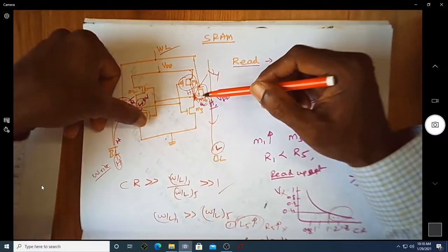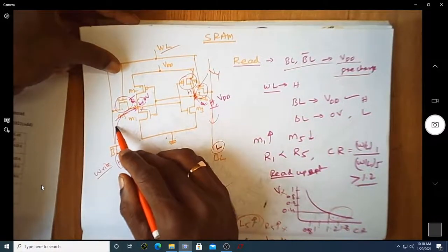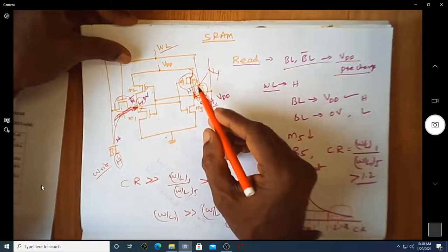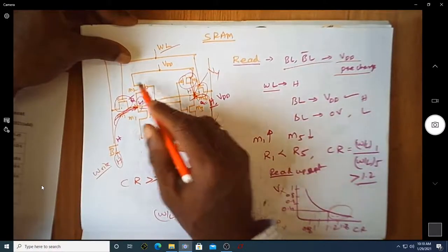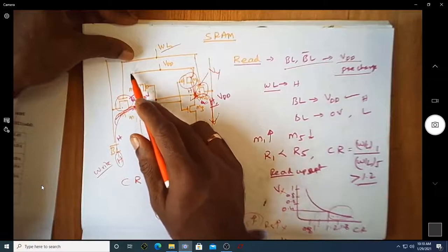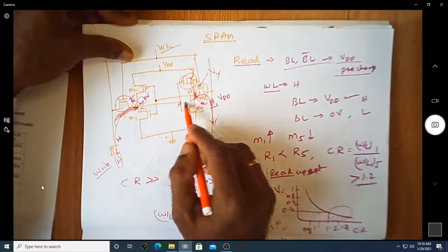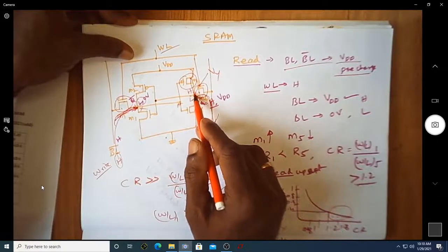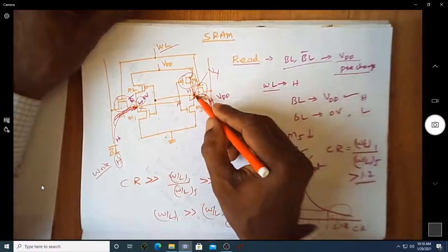so that this transistor turns off. When this is off, this also starts charging. More than that, whenever this totally discharges, you are going to have a low voltage. When this is low, this NMOS will turn off and this will turn on. Whenever this turns on, the voltage here rises. When this is high, what will happen to this? The high will come over here and this will be low. So whenever this turns on, the voltage that was stored here will also go to 0. So you will actually be writing a low onto this line.